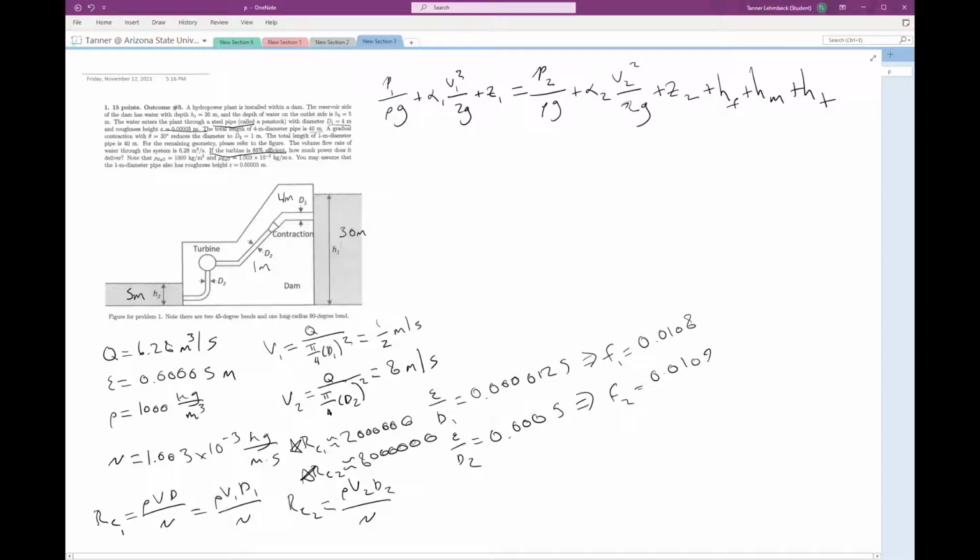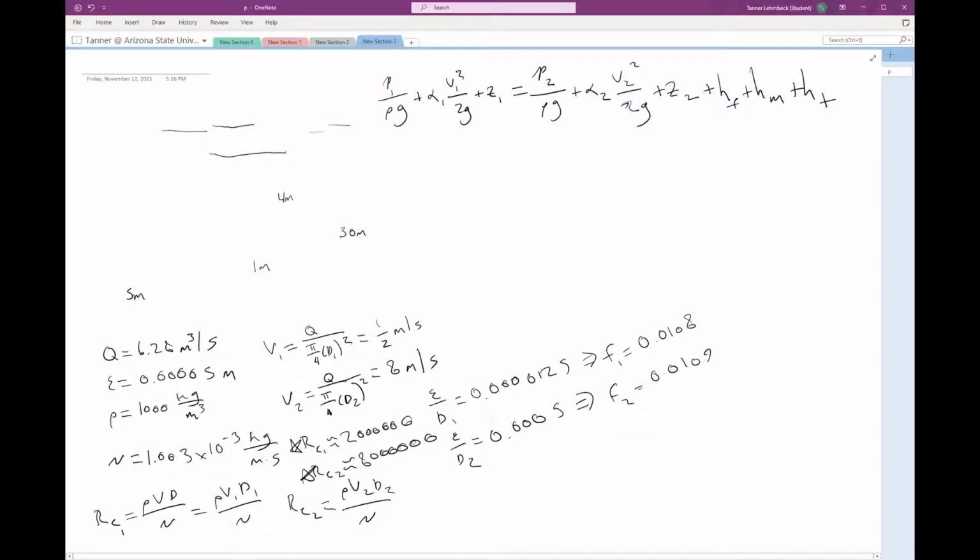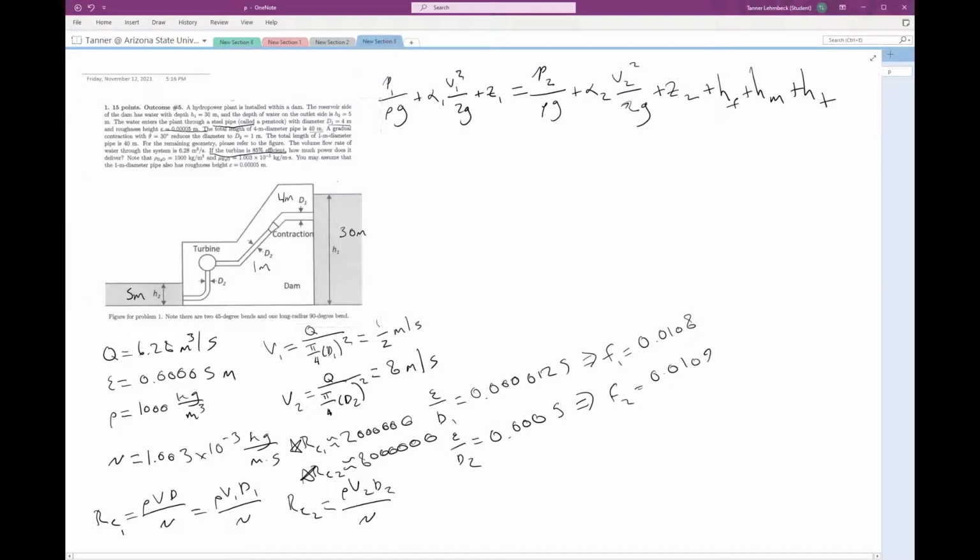So at this point, we'll make just a couple assumptions to simplify this Bernoulli's equation. Station 1 is this free surface here. Station 2 is this free surface here. Both of those should be just exposed to atmospheric pressure, so they're both the same, and they cancel. We're assuming that both of these bodies of water are reservoirs. And if we're dealing with a dam, that's a reasonable assumption. Meaning that V1 and V2 are both 0.